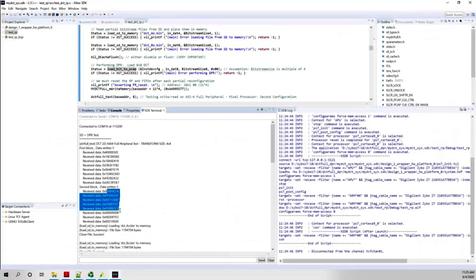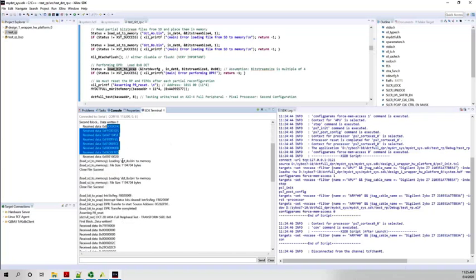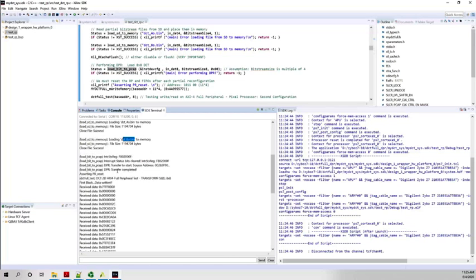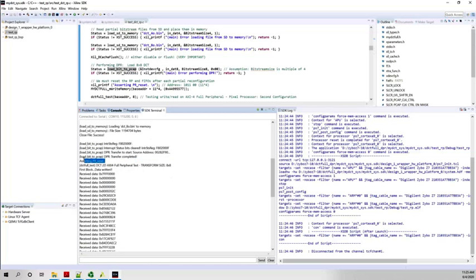You check this and you check this, and now here you see we load the bitstreams into memory, right? And then we reconfigure. This whole thing is reconfiguring it. After you reconfigure, we assert the PR reset, of course, by writing the special word, and then we test with 8x8.